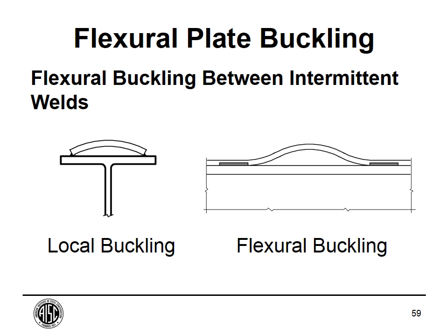So here's what I'm talking about between the flexural buckling and the local buckling. Local buckling, of course, is the traditional failure mode like this, and I've got this kind of on purpose. I put really small welds, and this is going to buckle kind of in a half sine wave like I've got shown, assuming that there's no restraint at these ends at the weld locations here. And the reason I did that is because that's what those particular equations that I just showed you are based on. It's based on pinned or simply supported plate edges. Now, that's not true for all of the local buckling equations in the spec, but for those I just showed you, it is.